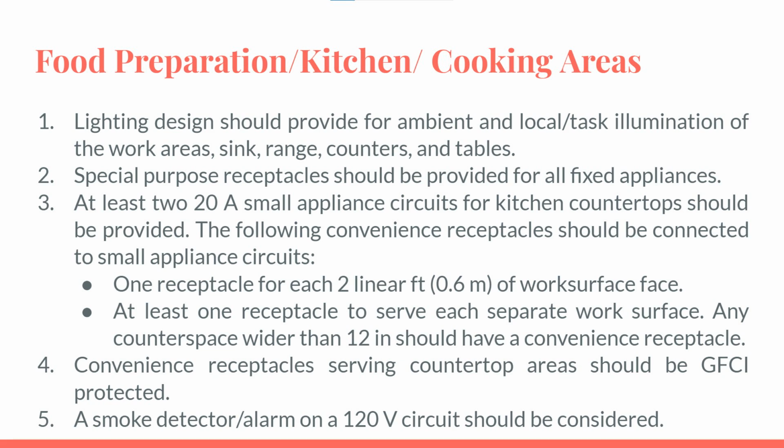Fourth, convenience receptacles serving countertop areas, except behind the refrigerator and those serving fixed appliances, should be GFCI protected. It is recommended that receptacles serving countertop areas be split wired. Fifth, a smoke detector or alarm on a 120-volt circuit should be considered.